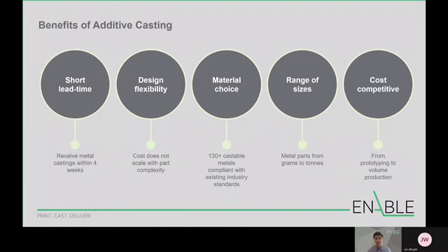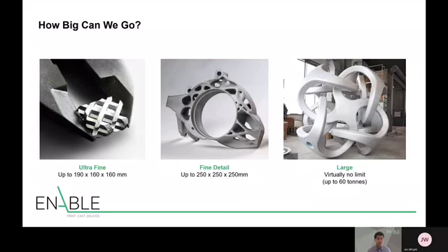Additive manufacturing has excelled at producing very small parts, but larger parts are less common. Unlike additive manufacturing, additive casting has virtually no limits on size, whether the part weighs a few grams or a few tons. Our additive investment casting process is comprised of a fine and ultrafine detail process, which can be used for small and intricate parts. Our ultrafine process is particularly suited to parts with wall thicknesses down to a millimeter and can even cast fine details, such as engraved letterings and logos.